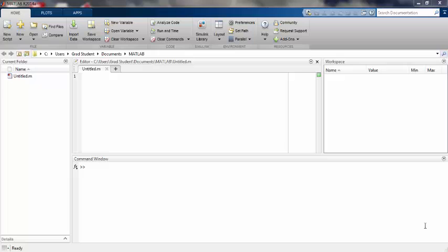The last portion of the lab has us building a numerical model of a 2-degree of freedom system. This will be very similar to what was done in Lab 5. That means to succeed, you should be comfortable loading in data to MATLAB, building a Simulink model, and then graphing the two responses together simultaneously. Keep in mind, this is a 2-degree of freedom system, so the time response data and the Simulink model will look different than what we had seen in Lab 5. Now for an example of the Simulink model, please refer to the picture on the second page of the background.